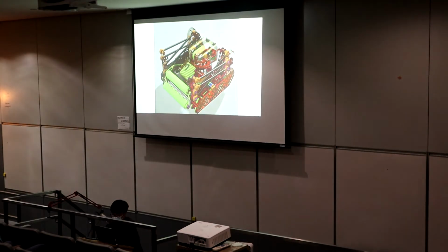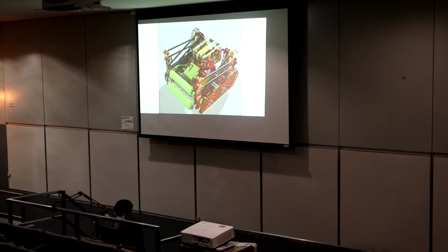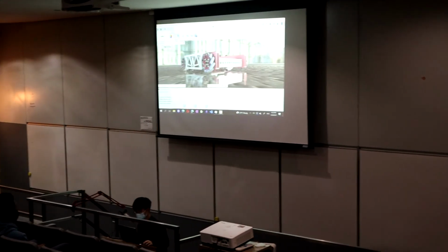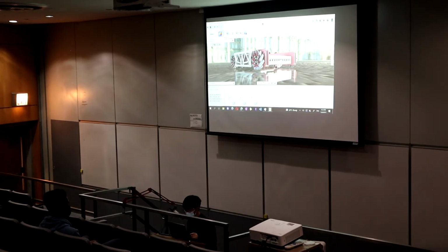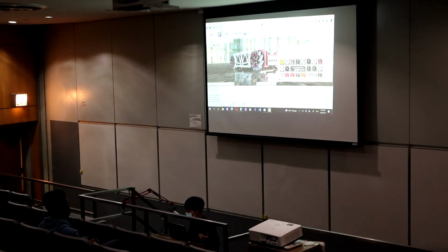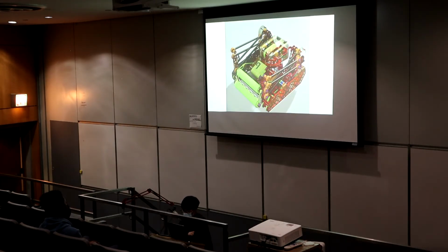So last year I designed a robot, and my friends were like, hey, let's make this robot mostly black, right? And you can see how that's really annoying to render, because if your appearances tab is a bunch of black things, you don't know what's a black piece of plastic or a black piece of aluminum, right? It's really confusing. So what I did was I applied all the correct materials to this robot, but I highlighted every key color. So green would be a rubber material, red would be a black aluminum material, orange would be a plastic material.